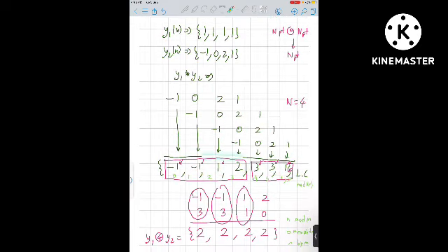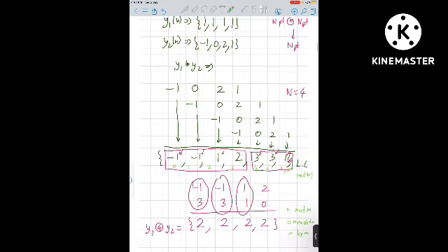But when we want to do circular convolution, what we do is that we were trying to use an n equal to 4 point sequence. So what will we do? We will try to break this into blocks of 4. Now here there are 3 elements, so I just append a 0 to it, and then I add these 2 blocks, minus 1, 1, 2, 3 and 3, 1, 0. Okay, now I add them, what do I get? 2, 2, 2. Okay, so this is the circular convolution of y1 and y2. Is this clear how I have done this circular convolution?